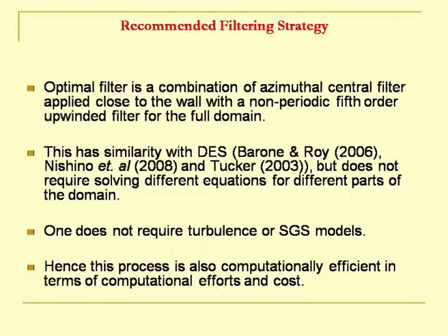See, azimuthal direction is a special direction because you have a perfect periodicity of the problem, right. So, you do not need to worry about this so called boundary closure. So, what happens is many a times people are very much attracted to use filter in the azimuthal direction because it is easier, you do not have to do additional problems, and then it also has the property of retaining its property uniformly across all nodes.